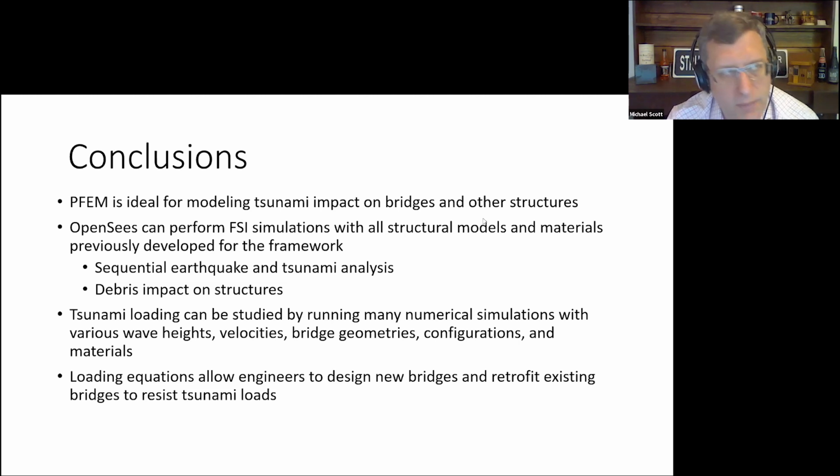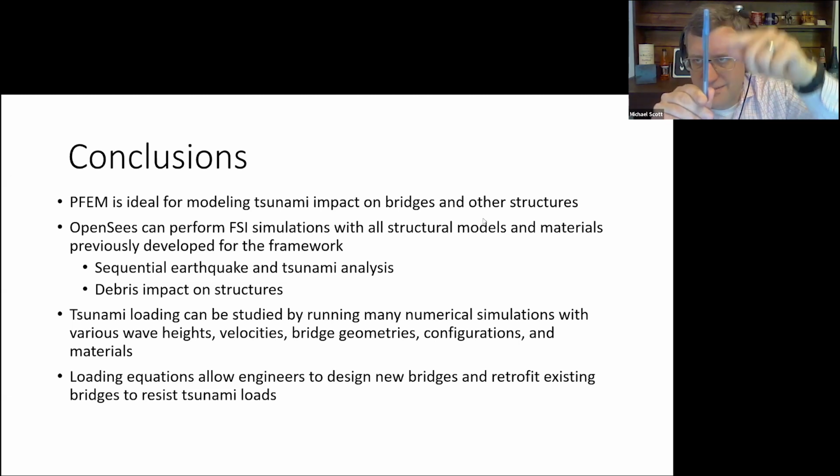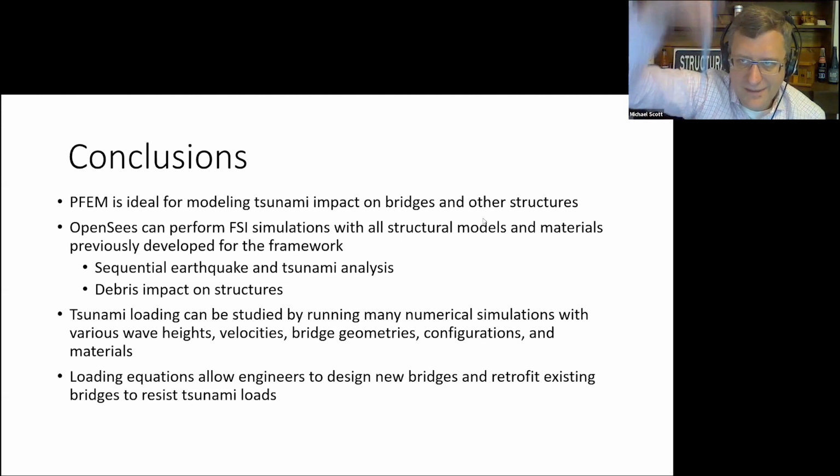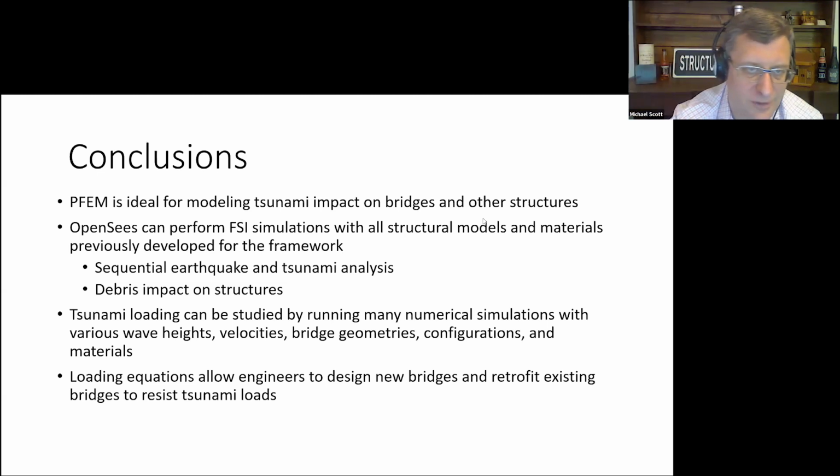I know in some numerical models, you can model that within your software, right? Just make this some beam elements, have an initial condition, and then just let the physics take over. But I know in some experiments the gate is lifted, or even in some numerical water tank experiments the gate just disappears, right? Or the water is held as an initial condition and you just let it go, like there's no gate at all, which I guess is kind of like lifting it very quickly. But yeah, it does definitely affect the flow downstream.